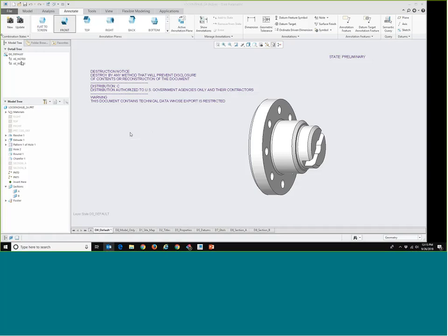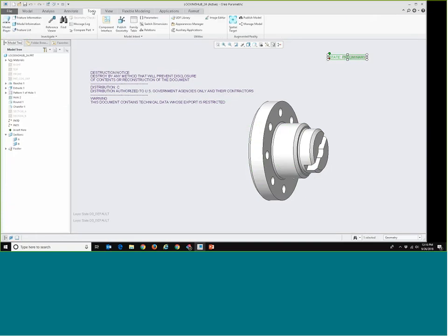When you select the first note, of course, it highlights on the screen, and you'll notice that there are a couple of text areas that highlight, and this may or may not come through particularly cleanly over the WebEx, but there are two pieces of text that highlight in gray, and that indicates that those pieces of text are actually drawn from parameters. Same thing with the second note. Again, the text that's highlighted in dark gray here comes from parameters. So to illustrate to the students where that comes from, we have them go into the parameters.